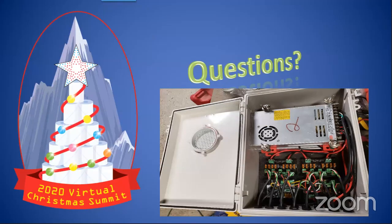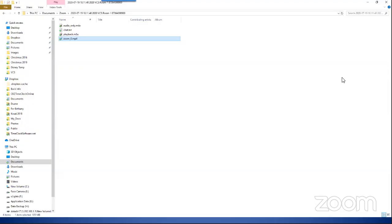What I try to do, just as an example, is I don't typically run my power from the ends of strings, because power is bidirectional, right? So I'll run it in the middle of strings. I'll still try to run it like the first string. Sometimes I'll tie it back into the controller because that's where it's coming from. But I won't inject at the end of a string like a lot of people will, because they think, oh, I'm at the end, I should do that. I'll do it in the middle of multiple strings because power is going to go both ways. You get a lot more efficiencies. I've run 400 pixels off of one power port.